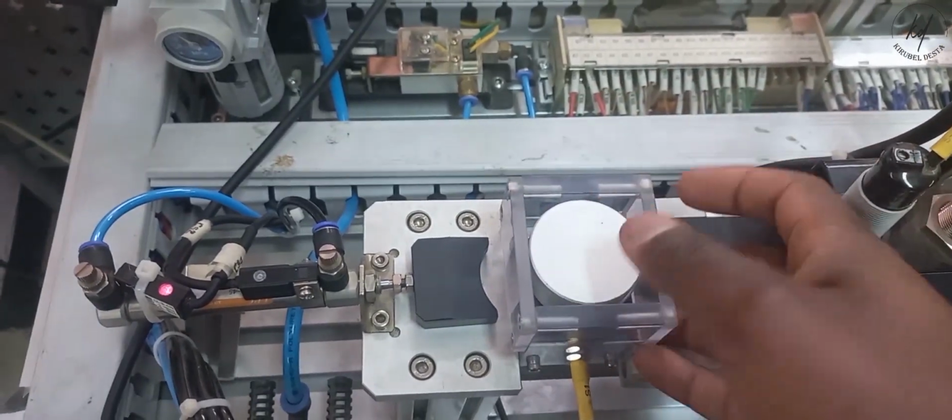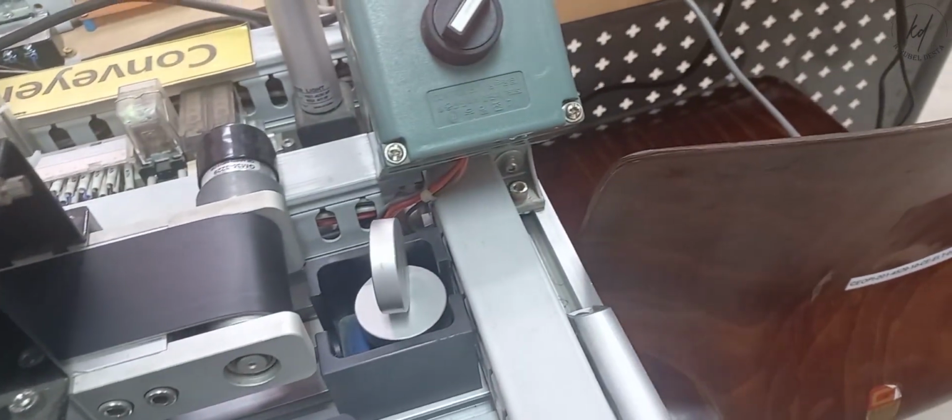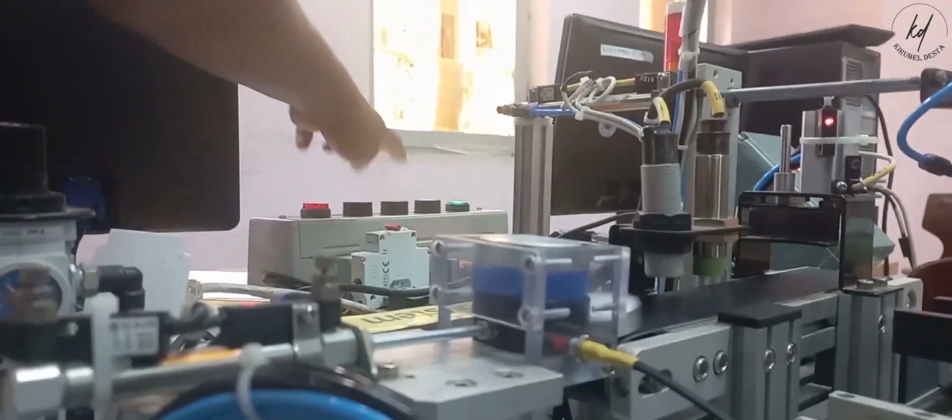The overall project could be explained as follows: the magazine sensor S1 is responsible for detecting any item that is manually fed. When the push button is pressed, the supply cylinder tries to eliminate the item from the box, and the conveyor starts to roll, carrying all of those disposed items and delivering them to the storage.